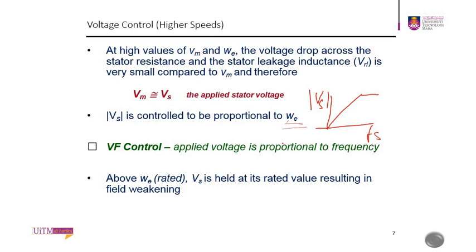So for V/f control, the applied voltage is proportional to frequency, and above rated frequency Vs is held at its rated value. This will result in field weakening.